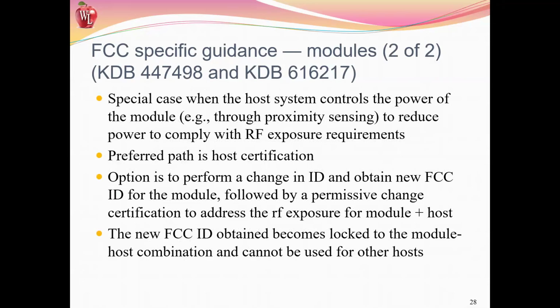And then special cases, where the host system controls the power for the module. They comply with RF exposure requirements through proximity sensing. That's a whole other category of how to make sure you comply with RF exposure. There's capacitive, or there's motion sensors that can turn the power down if they realize that you're closer to the device than you should be.